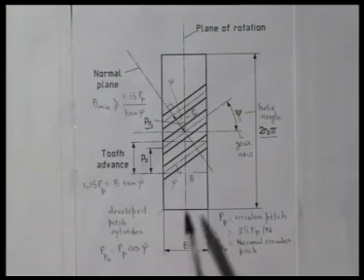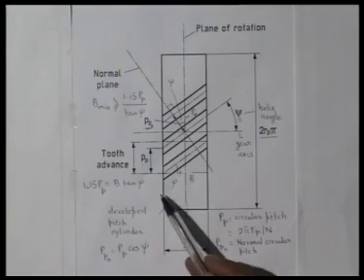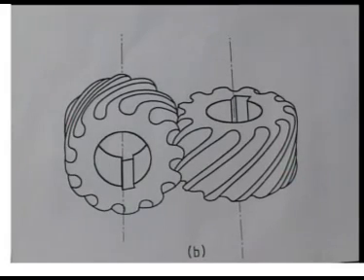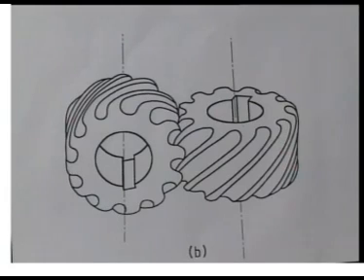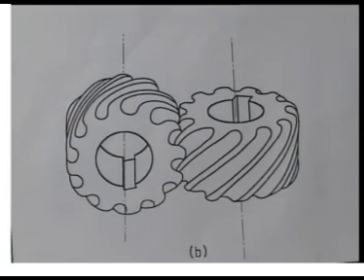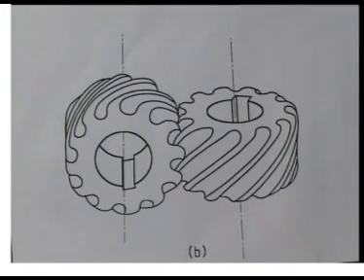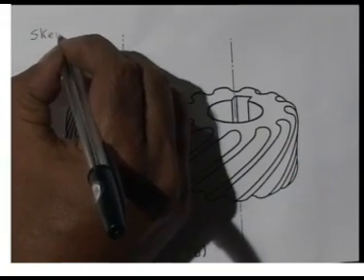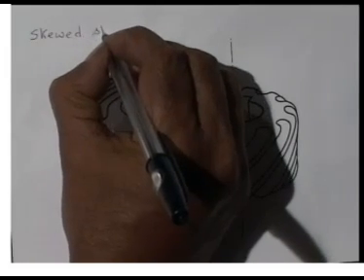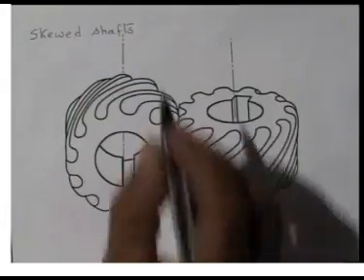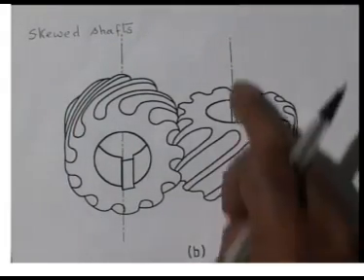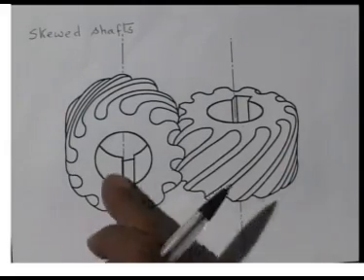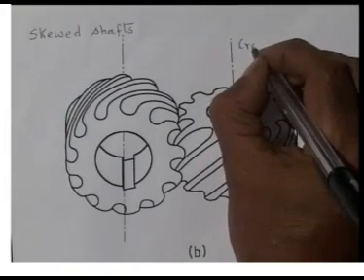So that finishes our discussion of the very rudimentary fundamentals of the teeth geometry of helical gears. So far we have discussed spur helical gears, that is, two helical gears of opposite handedness, like right hand helix and left hand helix, to connect a pair of parallel shafts. But helical gears can also be used to connect two non-parallel, non-intersecting shafts, that is, two skewed shafts. As shown in this diagram, this shaft axis is vertical, whereas this shaft axis is horizontal, and they can be connected by a pair of helical gears, and such gears are called crossed helical gears.